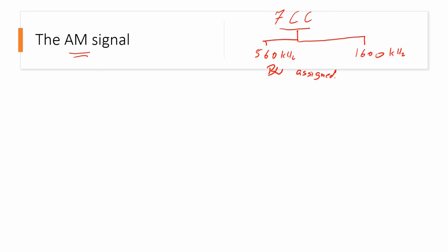This video is about Superheterodyne AM receivers. So we all receive the AM signal from radio devices, and the protocols which govern the spectrum come from the Federal Communications Commission (FCC). They define a certain spectrum, and that spectrum in most countries starts from 560 kilohertz and goes up to roughly 1600 kilohertz. And herein the bandwidth assigned to a given user or station is basically 10 kilohertz.